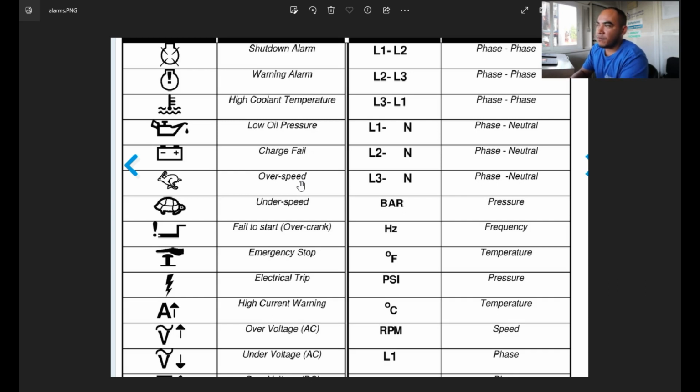What are the causes of this? I will give you some examples, like you have the shock load, overfueling, dirty fuel, or water in the fuel. Sometimes it will cause some of these alarms, because it cannot stabilize the running status of your engine.